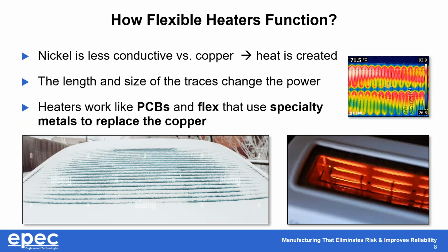It's also important to note that the length and size of these traces changes the power of the heater and how it's going to operate. The same is true depending on how hard you're driving the heater with whatever voltage. As shown here in the upper right, as you drive the heaters harder, they are prone to hot spots. Certain portions of the heater can be warmer than others. This also may be indicative of the thermal mass of whatever you're attaching the heater to. But this is important because if you try to push too much power through a heater, it can jeopardize its lifespan and its performance.